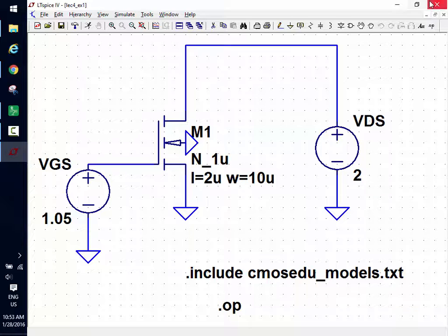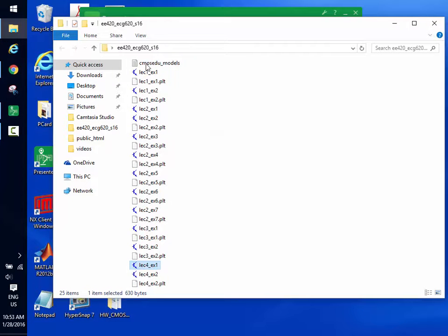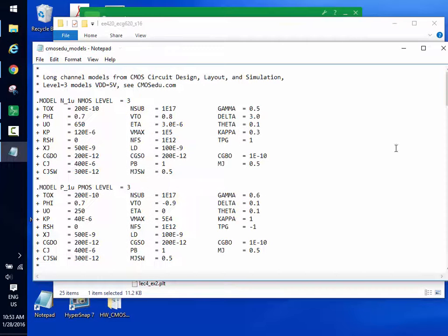Oh, remember that there's the sub-threshold current that flows below threshold. If you go look at the models, and we're not spending time on that because SPICE modeling of MOSFETs is a big deal, you have all these other parameters that influence the calculated threshold voltage. So there we're saying, hey, the zero bias threshold voltage is this. But we have all these secondary effects that come into play that try to make the device behave more like it actually does when you fabricate it.